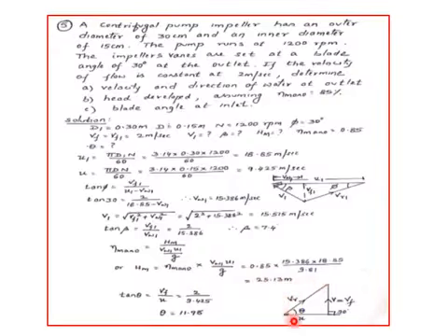But the inlet velocity triangle can always be drawn. Because V is always in the radial direction, this is U, and in the tangential direction is Vr. This is angle theta. Therefore tan theta is nothing but, because Vf is equal to Vf1, which is 2 meters per second, we know Vf and we know U because we have already calculated it. So tan theta is Vf by U, and therefore theta can be calculated.